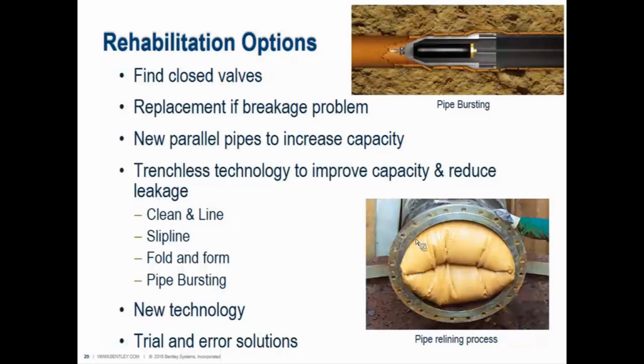If that rehab study is going to change the inside diameter, I would also include that, and include the proper actual real-world inside diameter for the lines before and after. That way you're really comparing the true difference in carrying capacity, volume, flow rate, and head loss that you're actually going to experience by performing this rehabilitation on the pipeline. So to do that, you'd set up two scenarios.